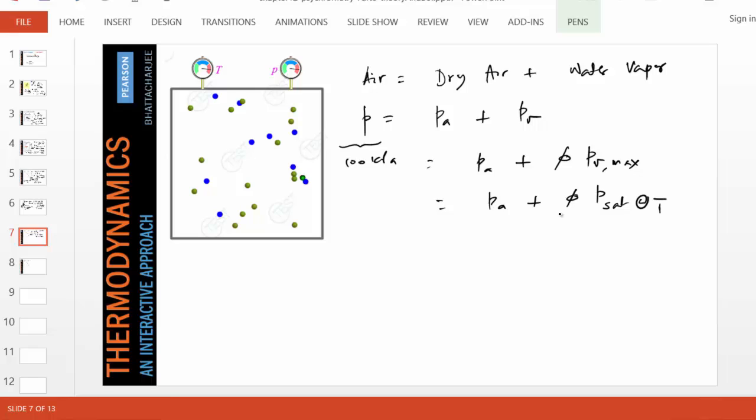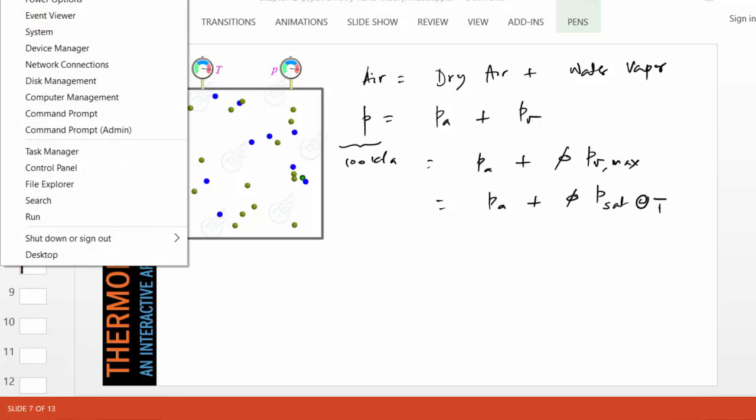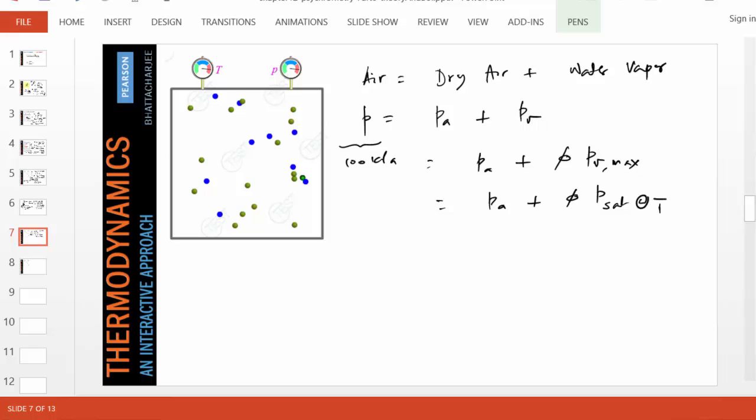It turns out that you can represent the state of the moist air in a PT diagram. Let me just explain. The temperature is also called the dry bulb temperature, essentially the temperature of the air. Why it's called dry bulb temperature, we'll discuss that later. So if you know PV, the vapor pressure, and the temperature, you can determine the state of air because the total pressure of air is generally assumed to be known, 100 kPa.